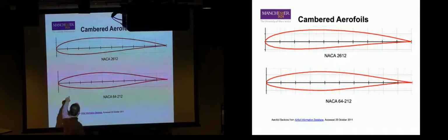And if we look at these airfoils, here's quarter chord. Is there more curvature forward or aft of the quarter chord? It's easier to see in the one above it. There's more curvature aft. There's just more space aft. So it's going to be nose down. So cambered, standard, positively cambered airfoils produce a nose down pitching moment. Okay? That means we have to correct for that.